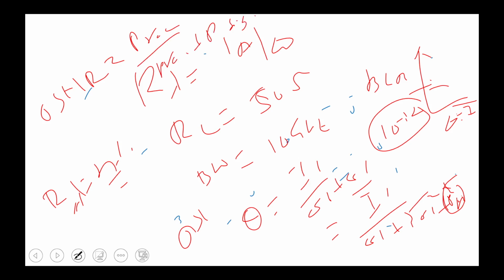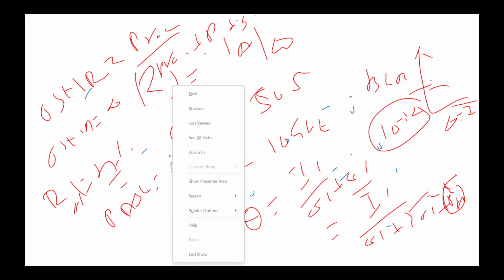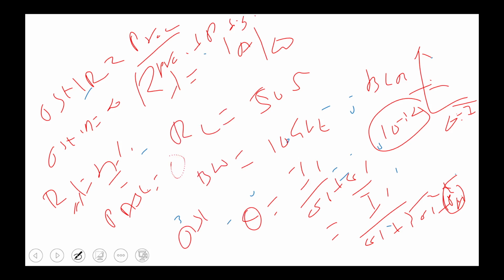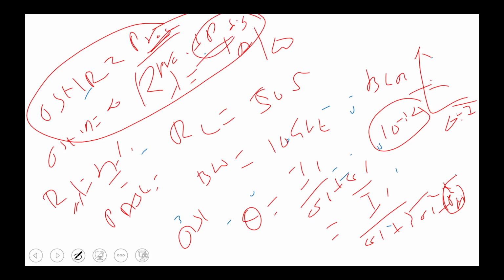When you are given the first case where your OSNR is infinite, it means the power density of the noise at the receiver should be 0. So you can calculate the P receiver power in that case. When OSNR is equal to 20 dB, from that, given PS, you can calculate in the case of 10 dB. From this formula you are given everything, so in this question you can calculate P receiver and P noise power. Go through the first and second questions, you get both things, and then you have to mention the value of OSNR, and from that you can get the P receiver value.